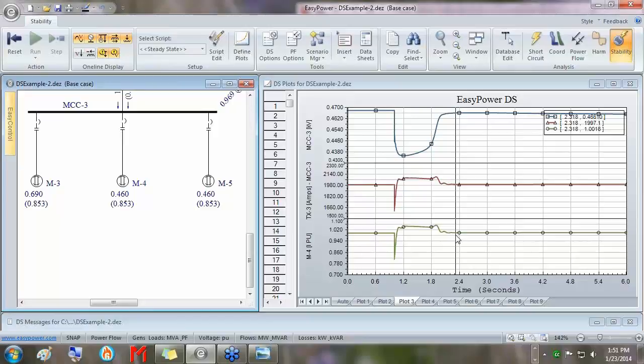That's something to definitely understand in your system. If you're ever near the edge of a voltage collapse or something in your system, note, you have voltage depressions like this, you can cause other things to draw more current and thus make it worse. Yeah, it'll just make the voltage depression worse because more current is now being drawn through, for instance, transformer 3 here that feeds MCC3.